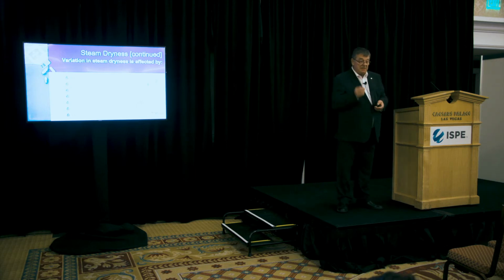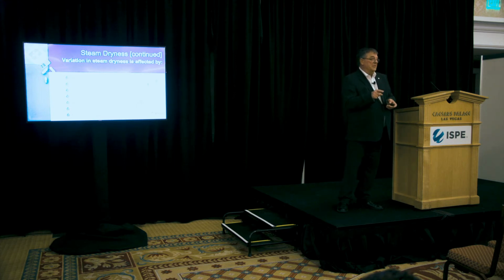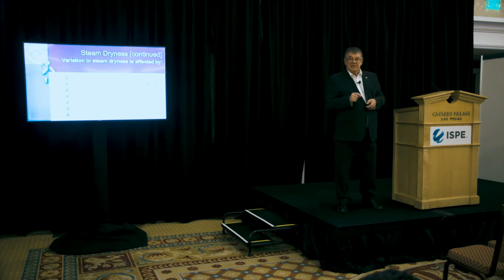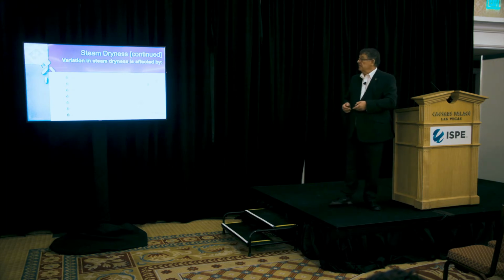Steam pipe insulation effectiveness. I sort of recall some experience here. I went to a very major food factory, which will remain nameless, and they insulate absolutely everything in the factory and cover it with very nice polished aluminium covering around the installation. Within a couple of weeks, it looks like the surface of the moon because the workers go around and poke it with their fingers. So it means that insulation performance can vary. Bits can drop off, especially in tight spaces.